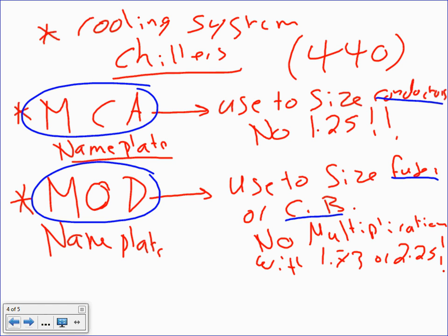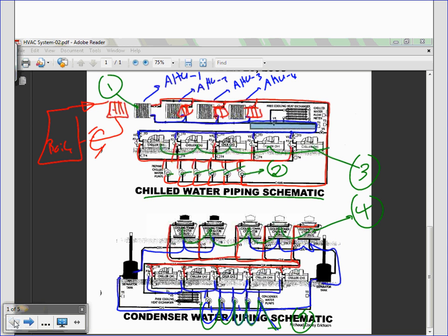This is really, I went way beyond what the chapter talks about, just to show you how the systems work together. When I showed you guys all these systems, let's go back all the way. All these systems, right? We put them most of the time, guys, in a big fat switchboard or switchgear, and we call it a mechanical panel. That's what we did in our project. We did almost all the mechanical equipment. We put them in two mechanical panels, except, I think, the chillers, we fed them directly from the switchgear. Everything else, we put in two panels: mechanical equipment panel 1, mechanical equipment panel 2.